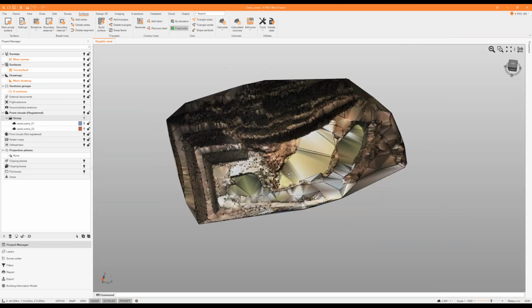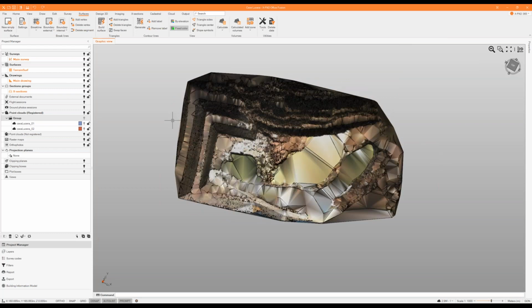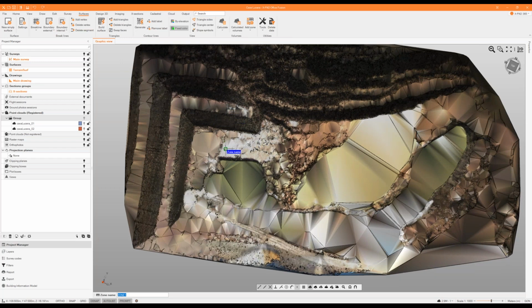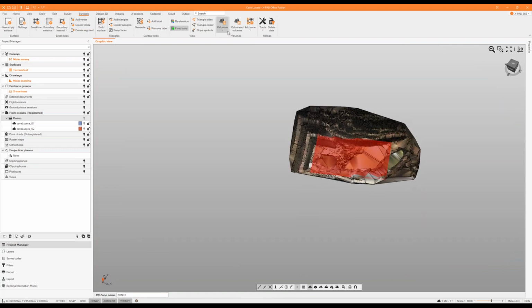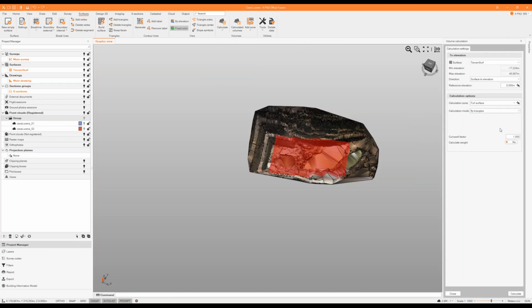Otherwise, if you want to create only a part of the report for a dedicated area, we can use add zone, and in that case, we can limit the calculation to a specific area. We have two options. By clicking on the arrow, we can use a predefined polyline or polygon. Otherwise, we can click here and directly enter the zone 1 name and use the different targets, use the different area positions. Stop command. So this is our area,